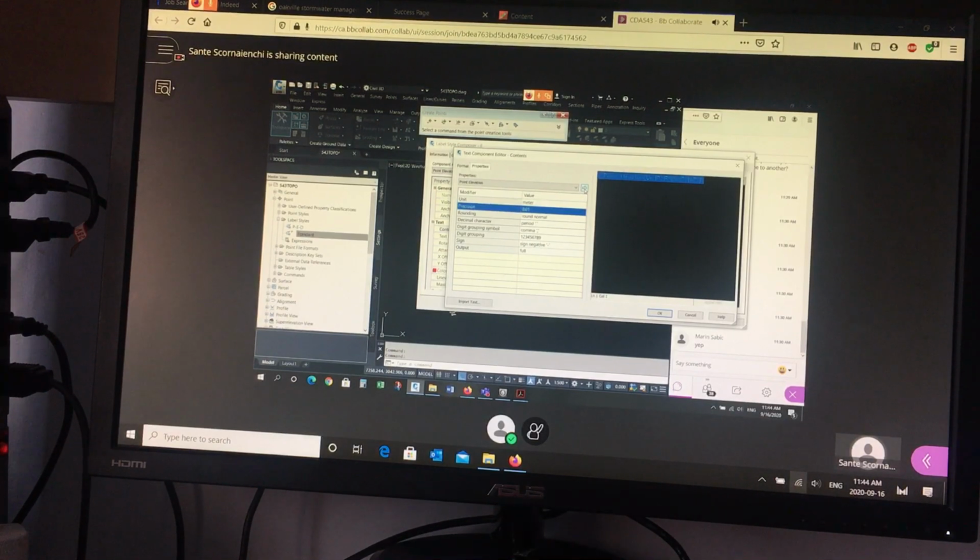I'll talk more about this later when we do lot grading. If I don't click that arrow, it won't write that new set of instructions into this text. See here it says P3, even though I've set it to 2. Watch what happens when I hit the arrow. Now it updates it to 2 decimal places.